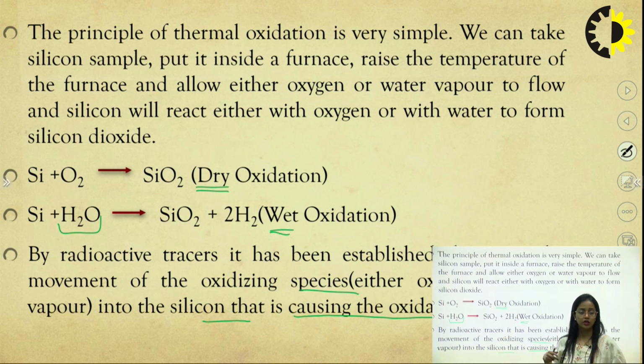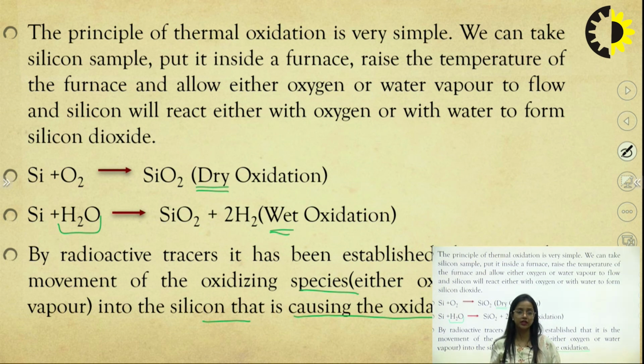So far we have studied epitaxial growth, and in epitaxial growth we have studied how the same type or a different type of material can be grown on the layer of another wafer, which we can name homoepitaxy and heteroepitaxy.